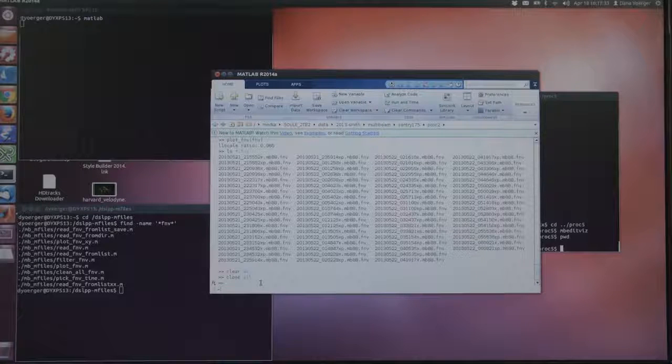In particular, one way to do the roll bias is to choose a section where we had the vehicle turn around and drive back down the same track line. In that case, we're going to be able to see the roll bias because we'll see the seafloor with the vehicle imaging it from one direction and then from another direction that's 180 degrees out. So that will greatly exaggerate the roll bias, allow us to see it. But we need to figure out which files we want.